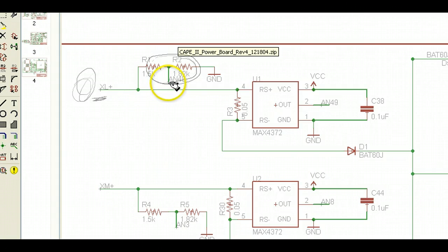We have to do that because the A to D cannot take more than 3 volts. So if you had 4 volts here, you got 3 volts here, and this goes essentially through a switch down to the analog input on the PIC. So progressing down the line, power flows in through this resistor. This resistor here is a very small resistor, 0.05 ohms.